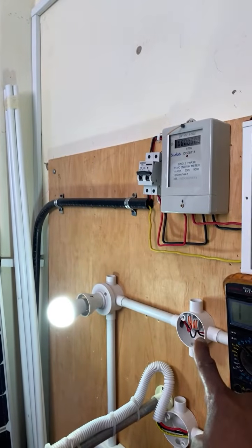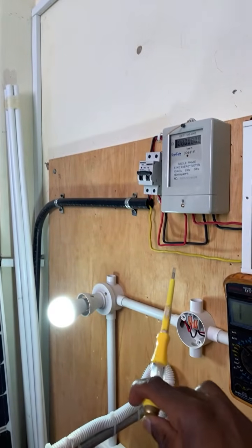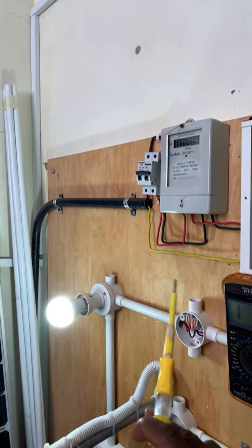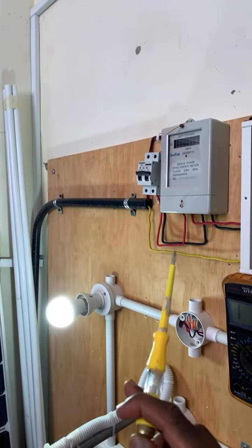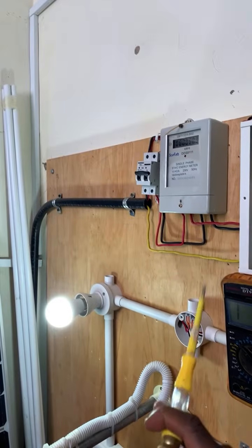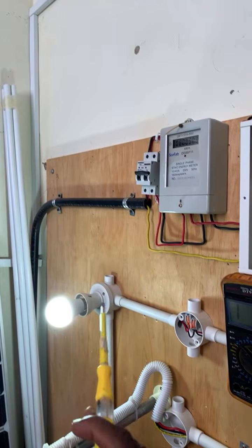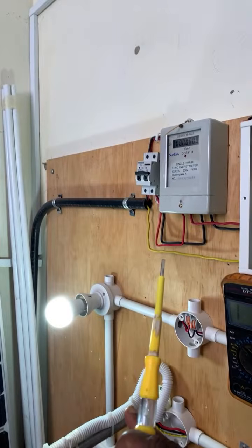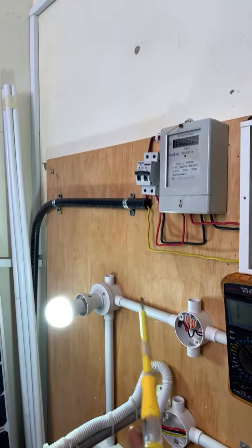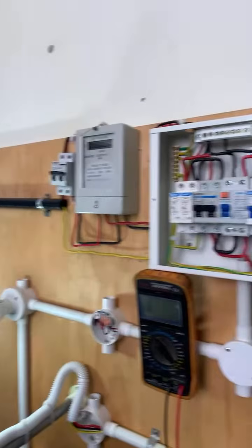So if you disconnect that neutral, when you use your tester, it will test on the phase the presence of current. But that does not guarantee that the bulb will turn on simply because there is current that is flowing in the line. That is why you need a multimeter, isn't it? Because assuming that there is presence of current flowing through the line, and then the bulb is not turning on, you will have a lot of hard time troubleshooting, finding out where the problem could be.